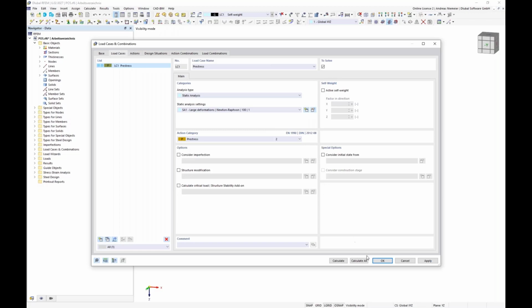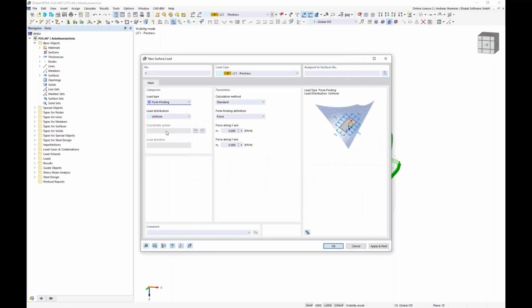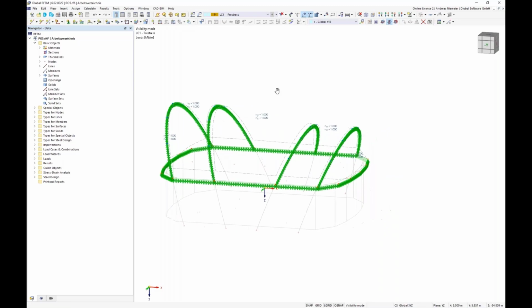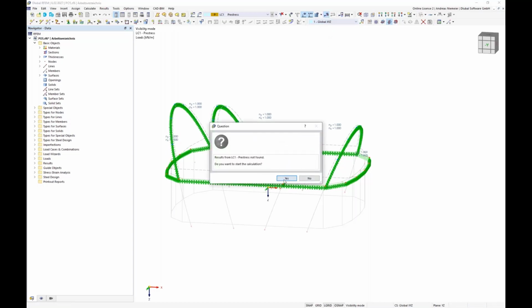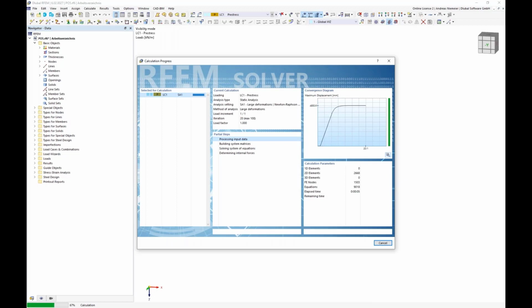In my situation, I deactivate the self-weight and apply on the surfaces itself a pre-stress by using this form finding load type. Here you can define which concept you want to use for this type of surface or shape. A standard method is acceptable, and form finding definition could be done by force or stress. We use force with 1 and 1 kilonewton in X and Y, or warp and weft direction. Now place these forces on the structure and we get a symbol of it, and now we can run our first form finding task and say, please program, find a good place of all finite elements to cover or to hold this pre-stress what we defined between these supported lines.